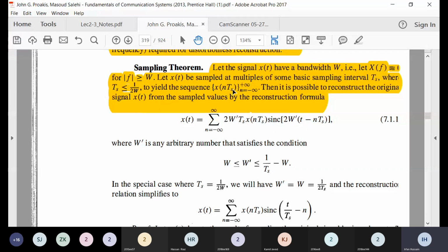Let us say 1 Ts, 2 Ts, 3 Ts, 4 Ts. In the digital representation, when you write x of n, x of 1, x of 2, what does that actually mean? The first sampling slot, the second. n equal to 1 means 1 Ts, n equal to 100 means 100 Ts. So at every integral multiple of Ts you are just getting the signal value, and that is the sampling.